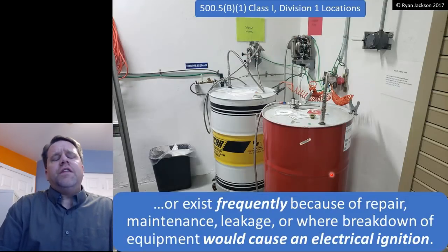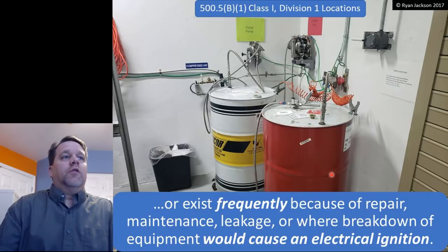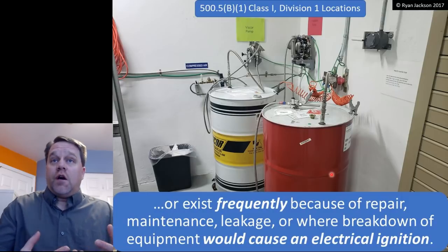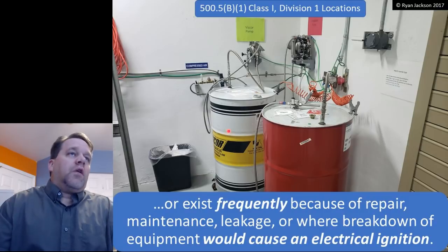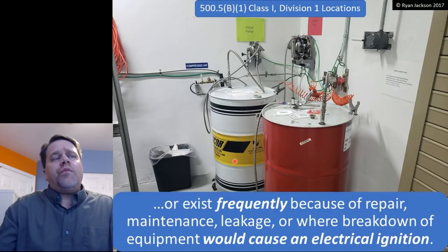Or the ignitable mixture exists frequently because of repair or maintenance or leakage, or where breakdown of equipment would cause an explosion, an electrical ignition. So what's the normal condition in this room? The normal condition for 23 and a half hours of the day is that this is all a closed system and there is not an ignitable mixture in the room.